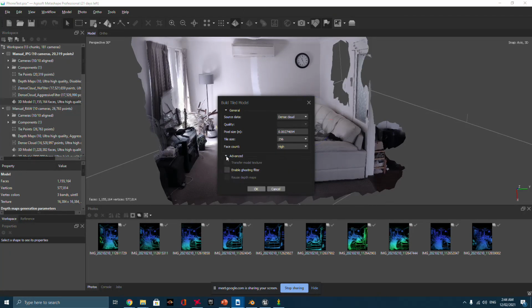ArcGIS Online. Yeah. It'll have levels of detail, so it might have 10 levels of detail or something. And then the tile size, if it's something at really high detail you want a smaller tile size, but then you could go something bigger. Are the levels of detail like zoom levels? It's its own level, so if you zoom out that far, it will be a really blobby simplified model, and when you zoom in, it has your main model, then 10 other models as well in there.